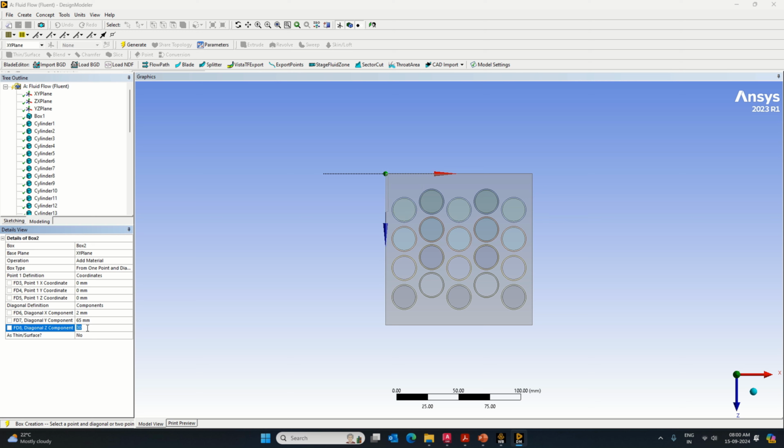Okay, now at what location we have to shift it? We have to shift it at a distance of, okay, so the distance from one end to the center of the cell is 15. So we have 1 as or 2 mm as a thickness. So I will take the distance that is equal to 14 from the left end. So that is here 14 I will put, so that it will be exactly at the center. Instead of add metal, I will make it slice metal, and then I will generate.